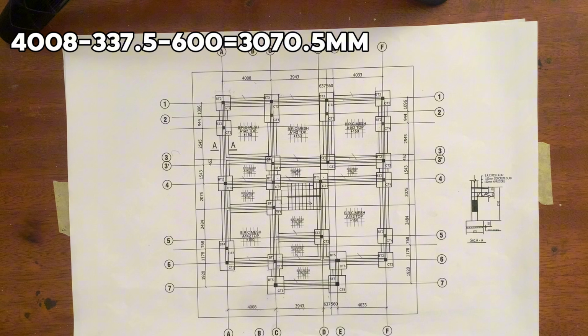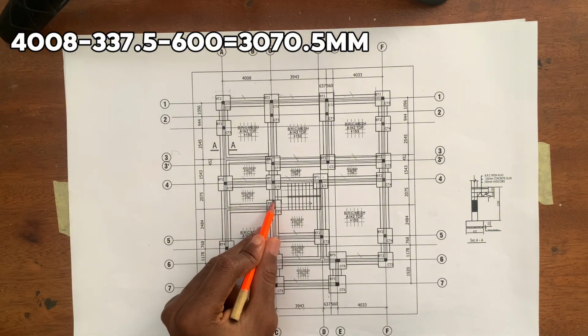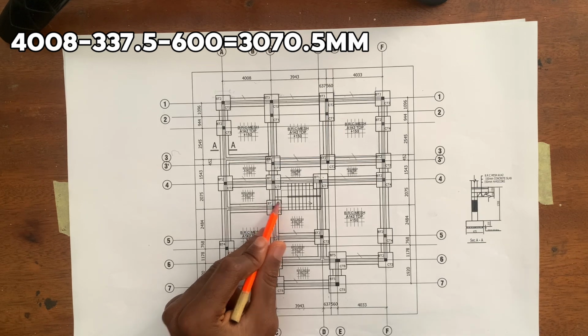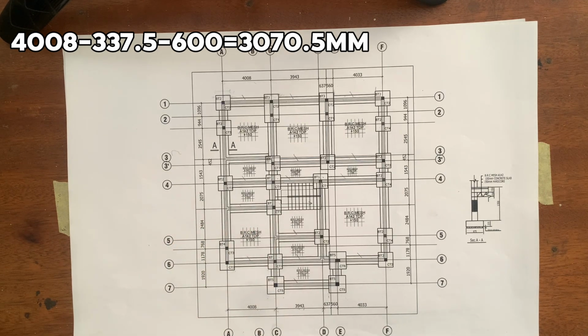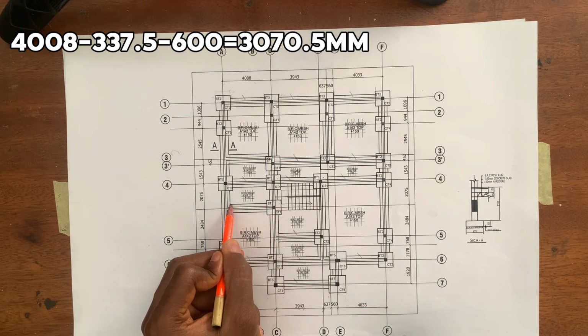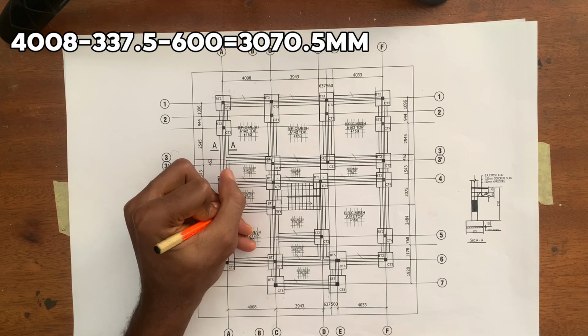We know that the distance from call out A and C is 4,008. We will now minus half of the width of our trench, which is 675 divided by 2, and then we will minus half of the length of base type 1. So base type 1, the length is 1,200, so half will be 600, so minus 600. So the distance for this trench here to here is 3,070.5. So we're not going to be recording it.